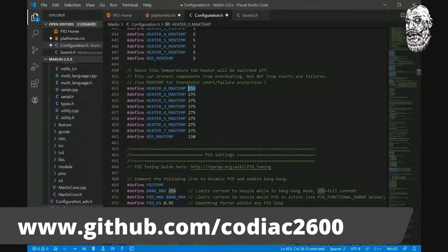So again, this is the basics. If you have a Creality printer, the reason they firmware limit the max temp is because that little plastic PTFE tube off gases a neurotoxin once it reaches a certain temperature. If you print at that temperature or above, you begin to release a neurotoxin, which won't kill you, but over time can cause issues.